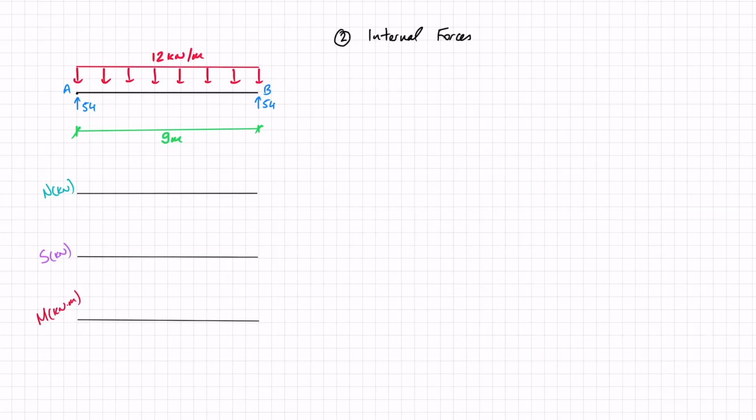So, as you know, whenever I want to calculate the internal forces, what I like to do is draw underneath the actual free body diagram with the reaction forces, space to find my axial load, my shear force, and my bending moment diagram. That's really helpful because it allows me to just step by step fill in these graphs and see also what the correlation is between shear and moment. Let's start off by deciding where we're going to cut this beam.